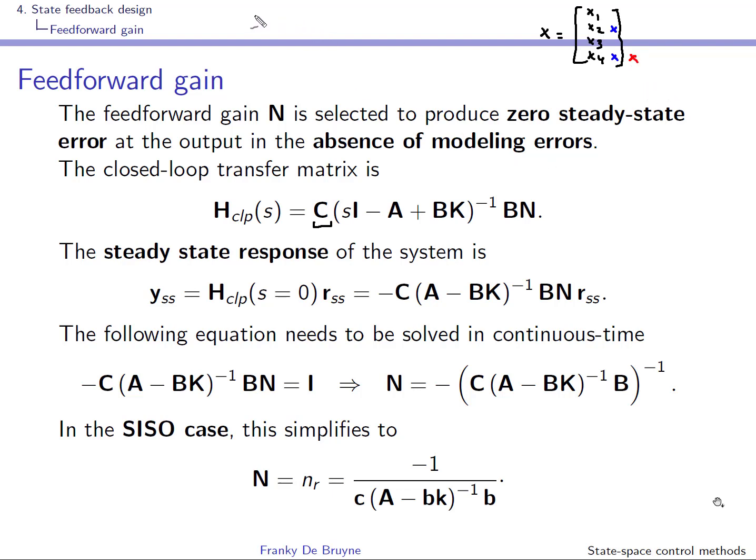Well, really there are three situations for the C. If you implement your model, for instance, in MATLAB Simulink, and you want to have a look at all the states, what you will simply do is y is equal to Cx, and since you want to have a look at all the states, you'll say that C here is the identity matrix of dimension 4.